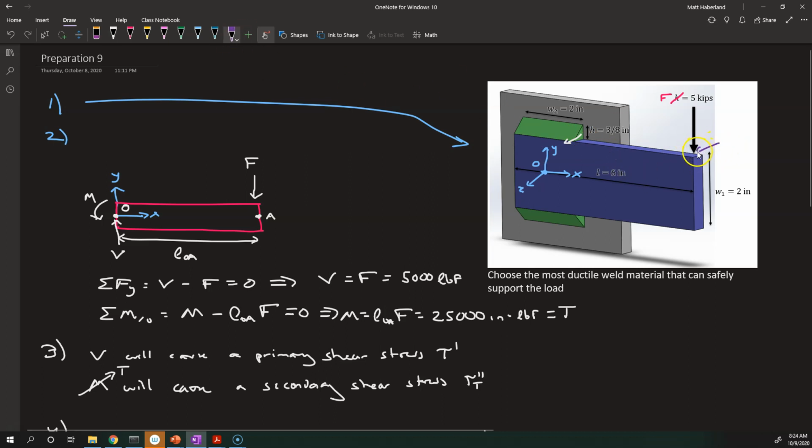So if this force were acting in this direction, then we'd get these out of plane stresses. And they'd be very much like when we've analyzed beams before, we'd have the same sort of thing down there. They'd be linear in their magnitude away from the centroid in this direction. Right? So the ones that were greatest in magnitude would be at the extremes, and then as you get towards the center, they're going to get smaller in magnitude as I've drawn.